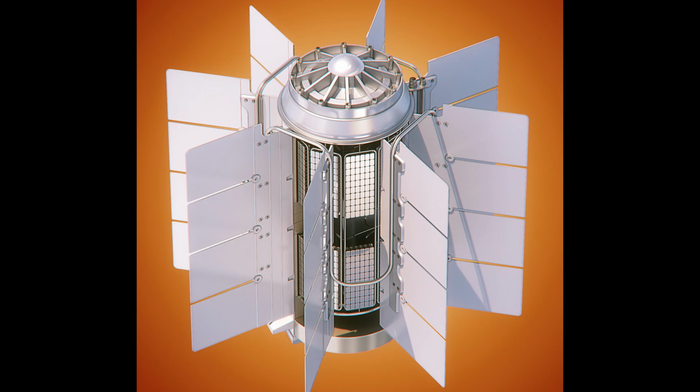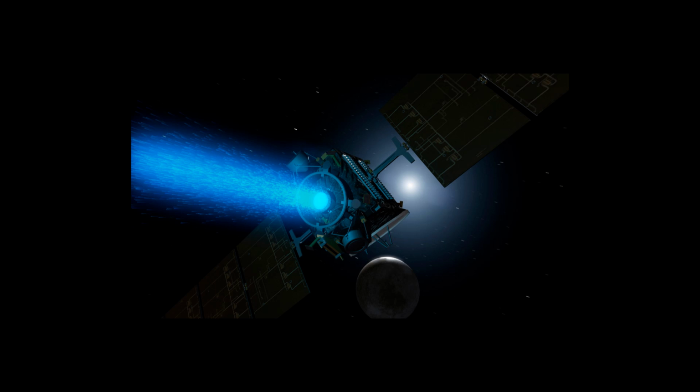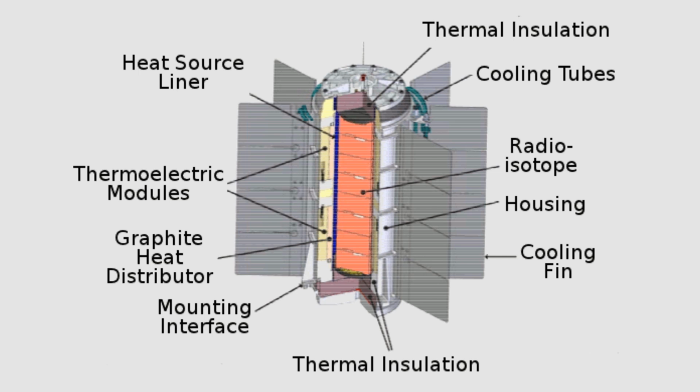The easiest and the only really seriously done way of nuclear space propulsion today is nuclear electric propulsion, which uses an RTG, a radioisotope thermoelectric generator, which isn't strictly speaking a nuclear reactor, but it uses a slowly decomposing nuclear fuel, and the heat generated by that is bled off via radiators, and the temperature difference between the slowly decomposing nuclear fuel and the radiator is used to produce energy via Peltier elements, for example.